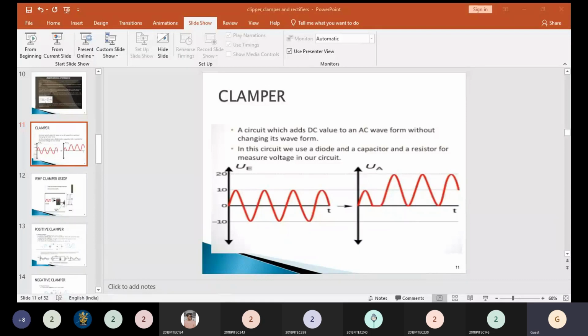So what is your power efficiency? Again, for calculating power efficiency, take the power at the output side divided by the power at the input side. That is your 40 and that is your 50 value. Converting to percentage by multiplying by 100, it is 80%.